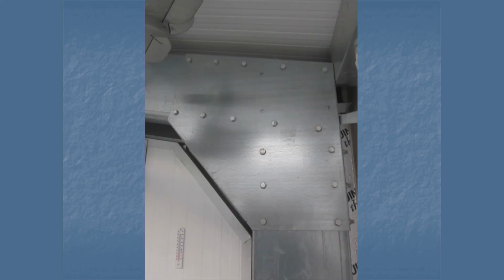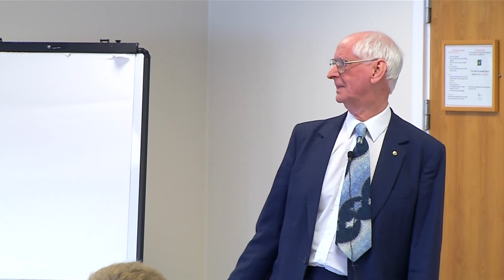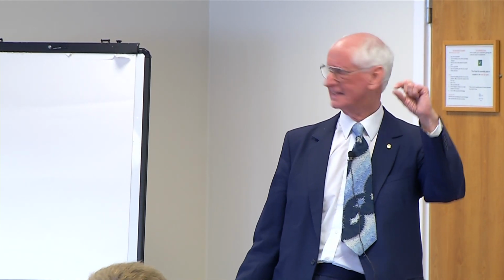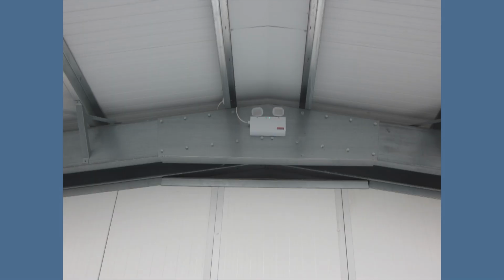And this is the knee joint. Again, no sign of any washers underneath the heads of the bolts. The manufacturer will probably say you don't need it. But really, when the metal's only this thin, I don't believe him. That's the apex one as well.